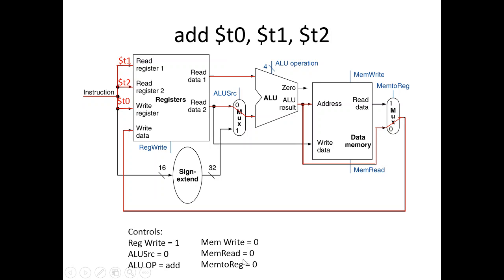So you notice there are 6 values here. I want you to notice that for later, because it's going to help select the paths through these different controls: mem write, mem read, mem to register, ALU op, ALU source, and register write. Now notice the write doesn't actually occur until the end, when it gets all the way written back.